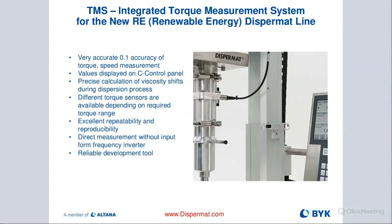With this particular machine, we use what's called the C technology control panel that allows us also to monitor these viscosity shifts during the dispersion process in real time. You can record that data, send it over to a computer, as well as all these other critical elements such as dispersing speed, energy input, torque value, obviously, but also the actual tape speed, RPMs, time, as well as temperature, are all recorded.